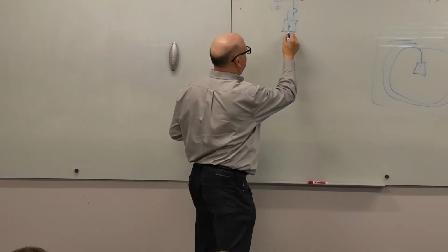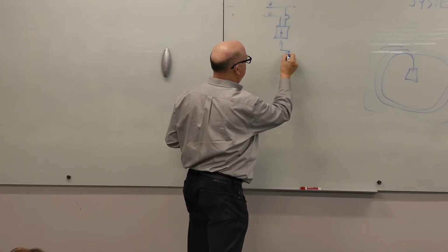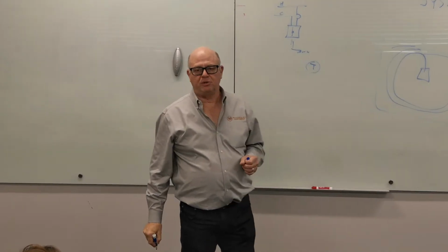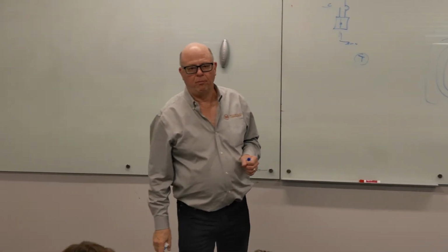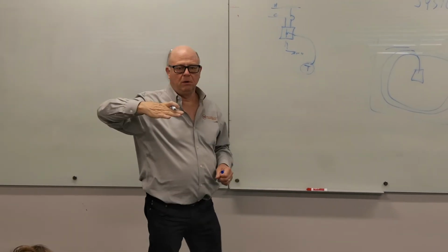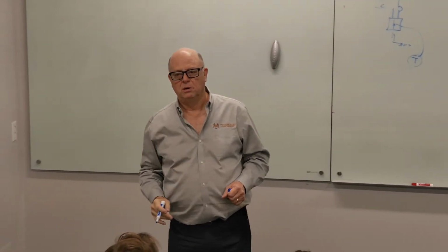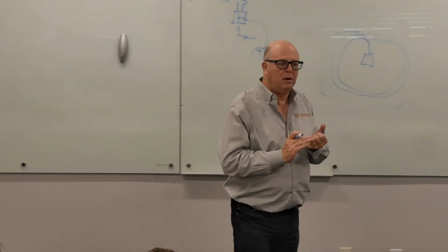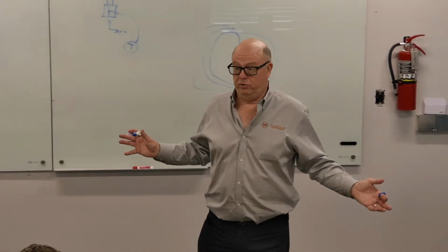And you'd have it coming out, and it would end up in a ceiling diffuser blowing into the space, and there'd be a temperature sensor of some sort on the wall. And this would go back up to a single actuator, which would just do this. Now, there's a lot of problems with this, but it's cheap, and it does a great job of temperature control.